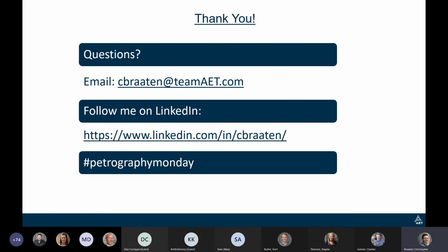And then is quartzite more susceptible given its metamorphic strain nature? Yes, quartzite definitely is alkali silica reactive because it has a bunch of strained quartz in it. And the Sioux quartzite, it's a really nice pink quartzite formation located down in South Dakota and southwestern Minnesota. That is known to produce alkali silica reactivity in concrete. However, it can be mitigated with fly ash or other SCMs, and it's a really good, hard, durable concrete aggregate when used correctly.